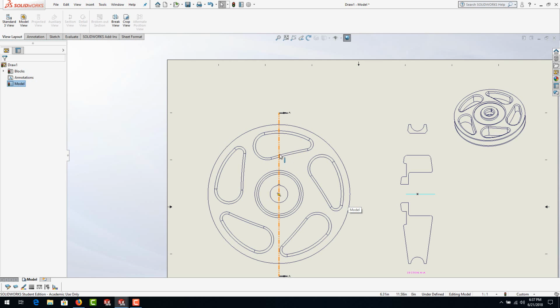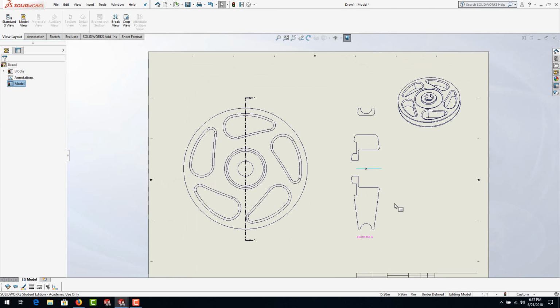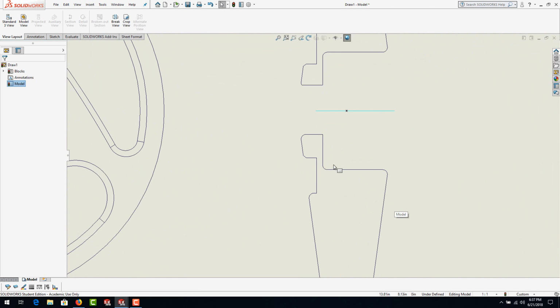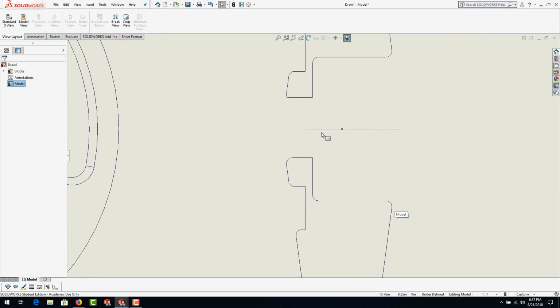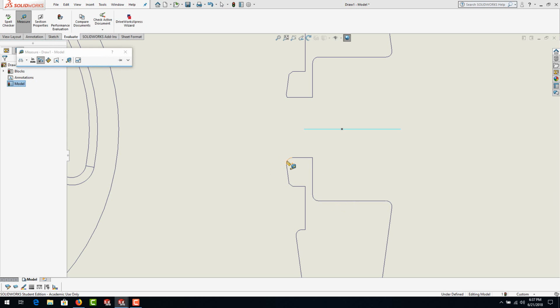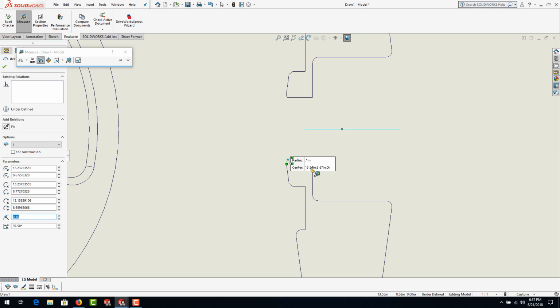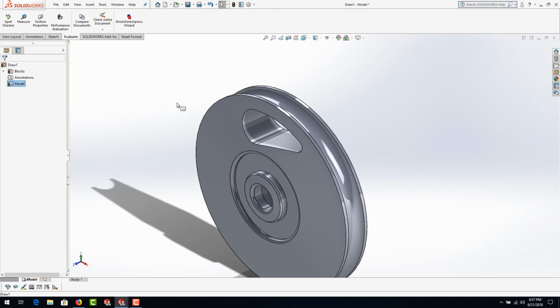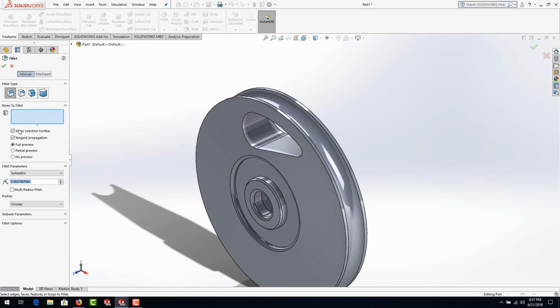So that fillet cut cross section right there, it was probably on the print somewhere that I turned off, but that's okay. If I recall, these are all pretty much typical. You could just go in here and select one of these under the Evaluate. Go to Evaluate, go to Measure, select that, and we see 0.1 radius. Now Control Tab back, and let's go to Fillet and set it to 0.1. And go ahead, you should be able to select this face here, and it will fillet everything.